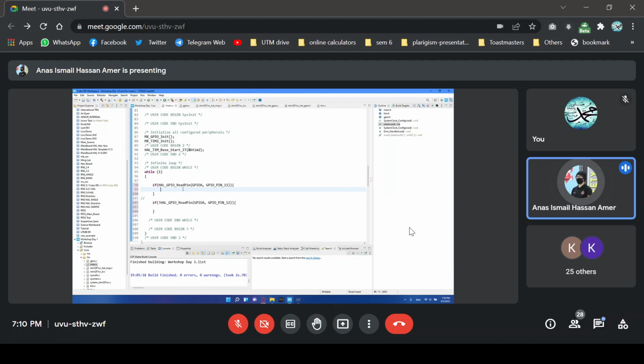So let's say if I click the first push button, we'll access the timer, which is timer 2 dot instance. If you just press dot, you have a lot of options. These are the initialization options and some other options. But instance is the timer register itself. So we'll click on instance. And then inside, we'll choose the ARR register. With this register chosen, we can just set it equal to something. So let's set this to 20K. This is the default.